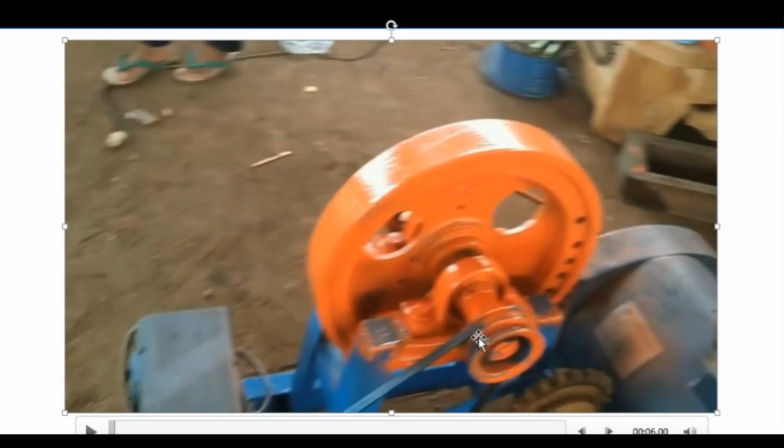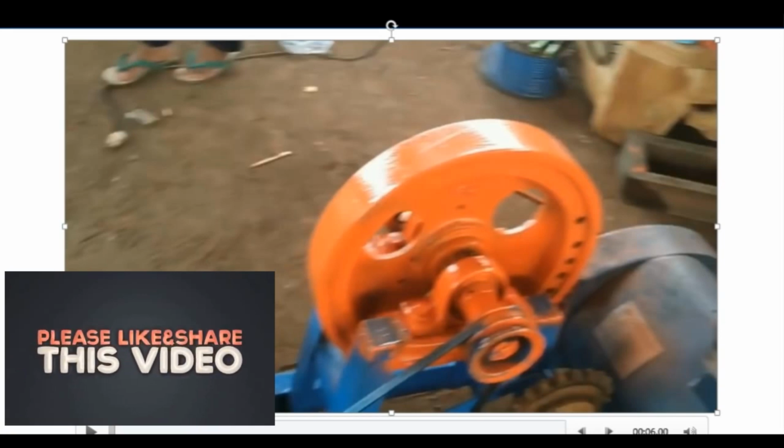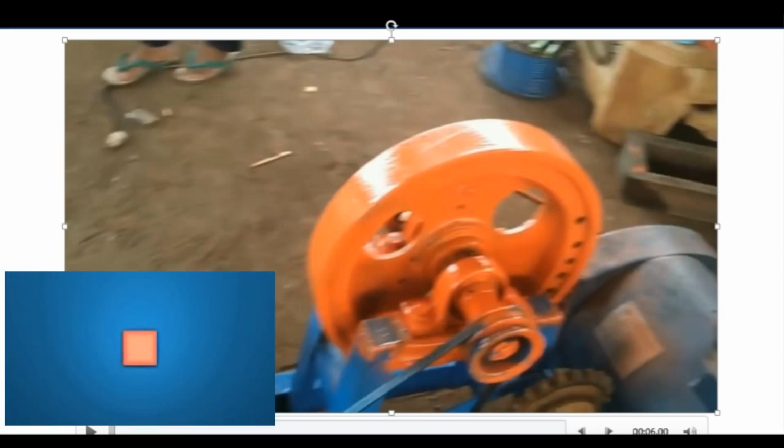Now, if the system wants to receive external power supply, it will supply and the flywheel will turn. The flywheel will turn until it reaches a point where it will be switched over to the generator here. The generator will then start supplying the voltage that is needed to the motor, and from the motor the flywheel still rotates. The flywheel is still in motion while the generator is feeding the motor, and the motor is also rotating at very high speed, giving feedback to the flywheel, and the flywheel also keeps the motion.